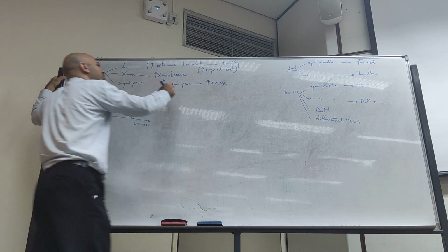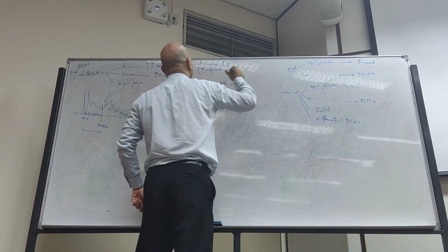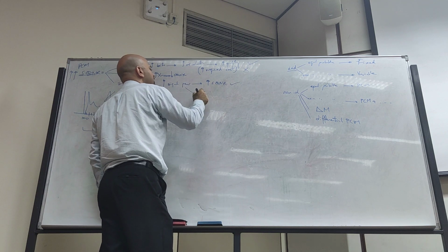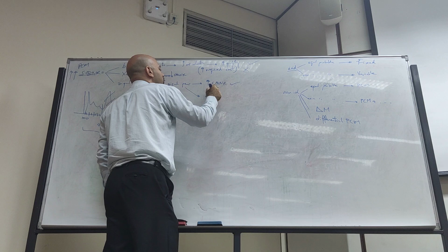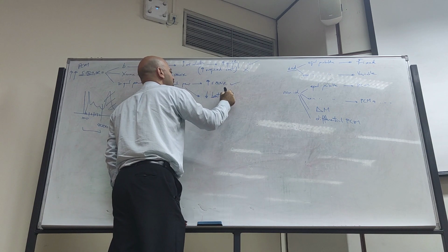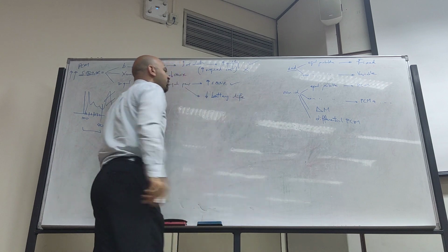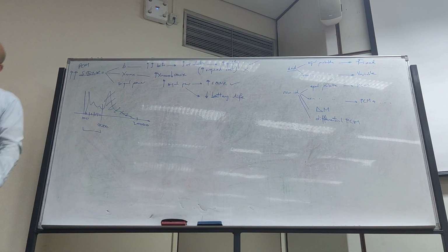So here, increasing the signal power, this is good, but also this is bad. Increasing signal power is bad because you will consume more of the battery if it is a handheld. So you will decrease the battery life. What else? Whenever you transmit, you can increase the power to whatever value you want. Do you see any disadvantage of increasing the power?